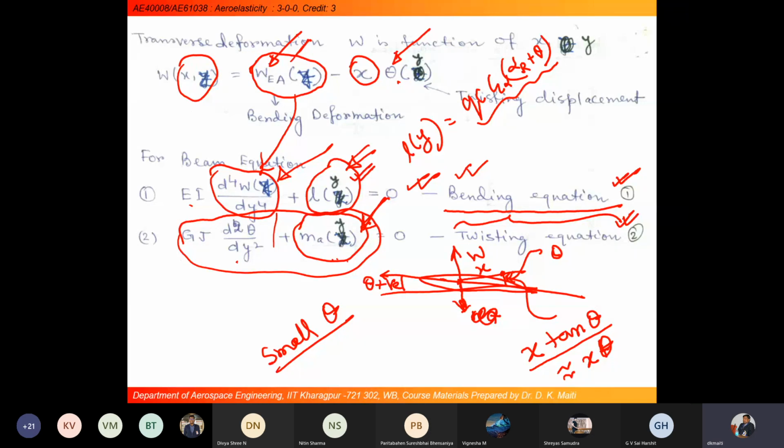That is why, in an aeroelasticity analysis, bending usually does not influence the deformation. If you look at the beginning, I discussed why we have taken the modal concept. We have taken only the torsional mode. We have not considered bending and torsion together for the aeroelasticity calculation.